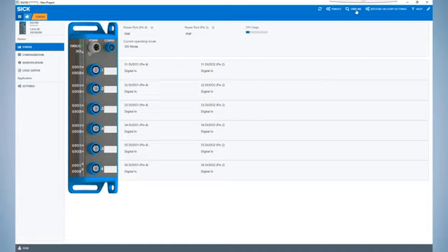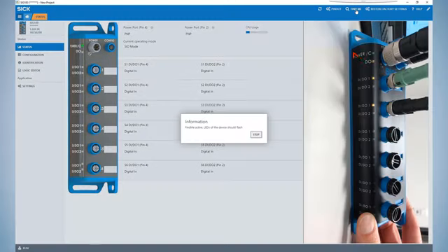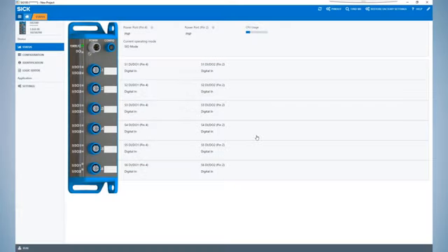The Find Me button will simply activate the Find Me mode of the SIG100. With Find Me active, the DO LED of the M12 power port will flash on and off. This makes it easier to physically locate the SIG100, which is currently connected for configuration. Note that while Find Me is active, no other interface navigation is possible until pressing the Stop button in the